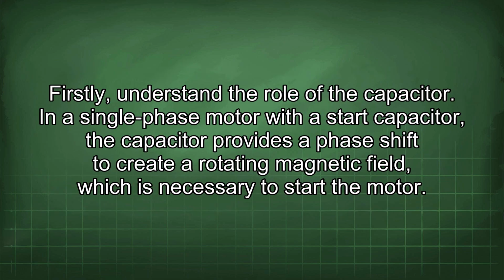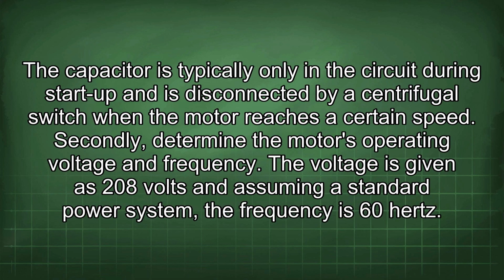Firstly, understand the role of the capacitor. In a single-phase motor with a start capacitor, the capacitor provides a phase shift to create a rotating magnetic field, which is necessary to start the motor. The capacitor is typically only in the circuit during startup and is disconnected by a centrifugal switch when the motor reaches a certain speed.